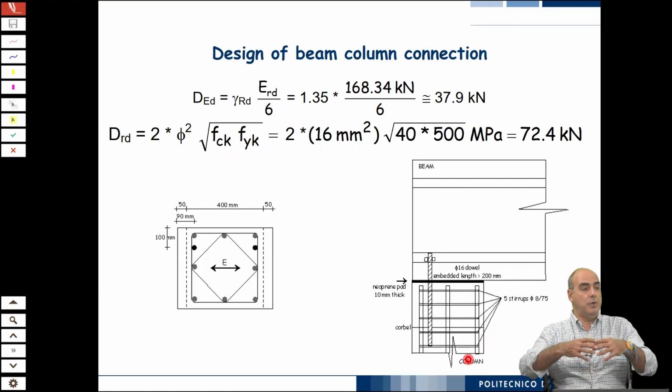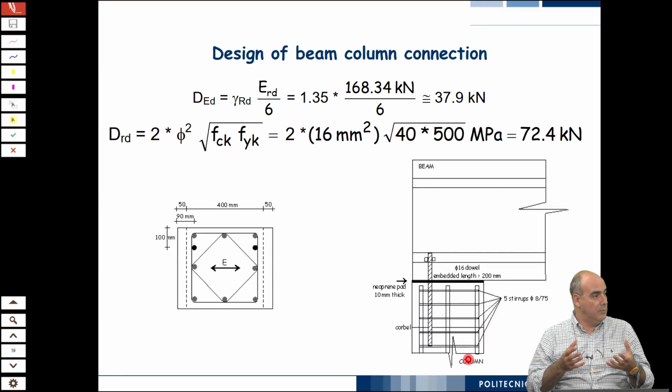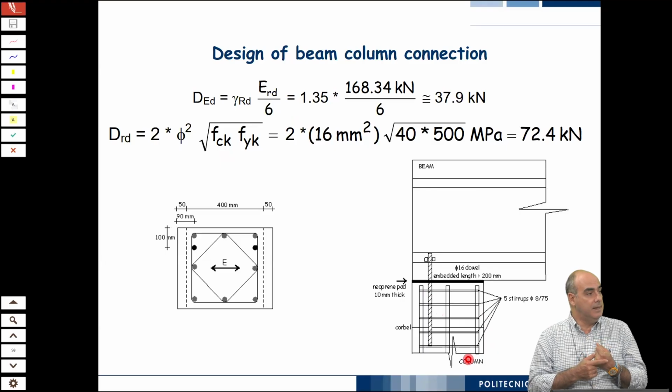And as a matter of fact, this is what they call the dowel strong mechanism. Strong mechanism is when you have enough material around. And so you can expect that your concrete crushes and you form a plastic hinge in the bar. So you have, and well, this is from their analytical elaboration. You have the paper, you can look for it.